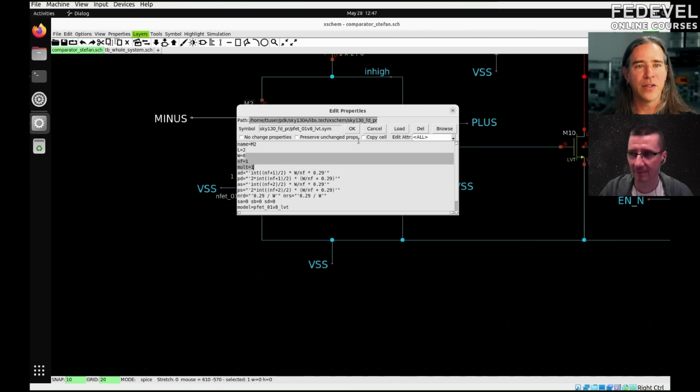The number of fingers is exactly the same width and length. It'll be the same transistor in essence, if you're only thinking of width and length, but it has more gates. Instead of being one long thing, it's chopped and put next to itself. So it has fingers like that. If you look at just the math, it's kind of the same thing, but it's not the same thing because you're changing gate resistance, you're changing capacitance and stuff.